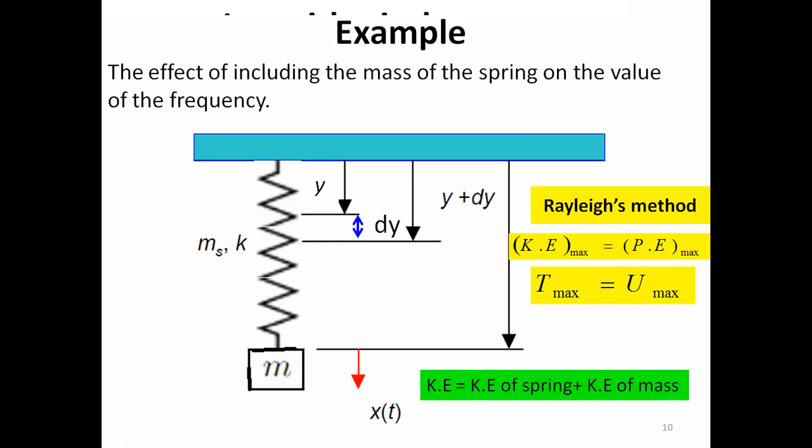So using the logarithmic method, very easily we could find out the damping ratio for underdamped systems. But for that, what you need is the plot. You need the plot when the system has been subjected to free vibration. So once we have that experimental plot, very easily using that method you could find out zeta.